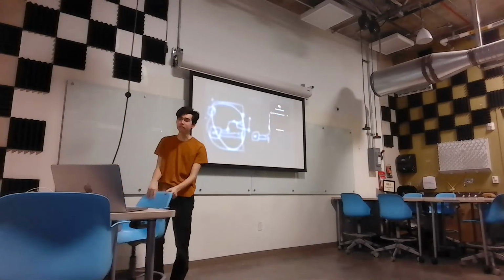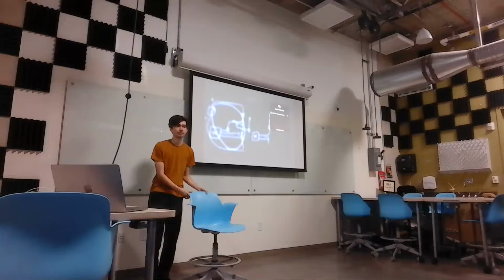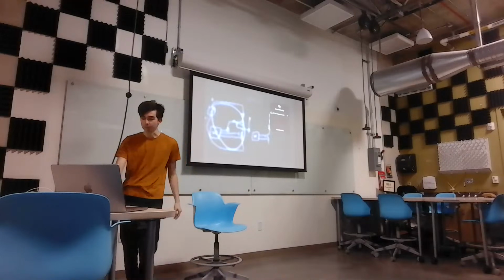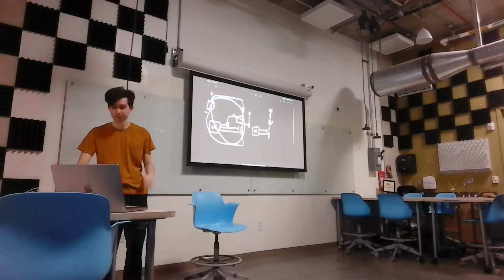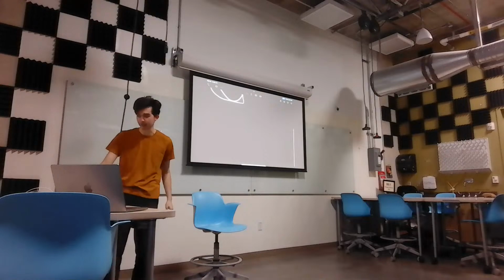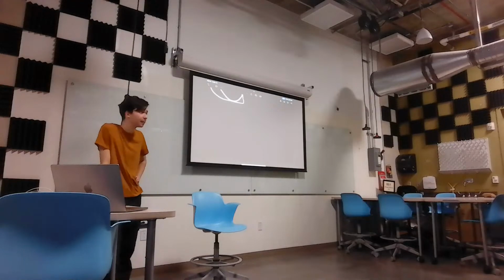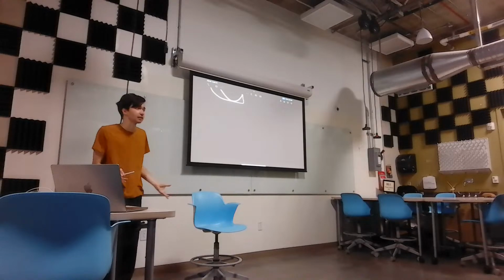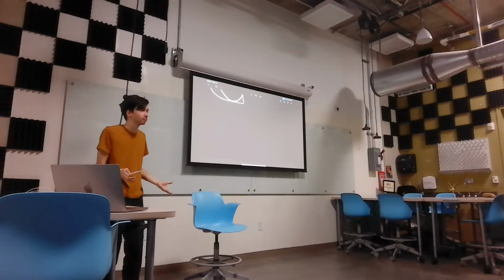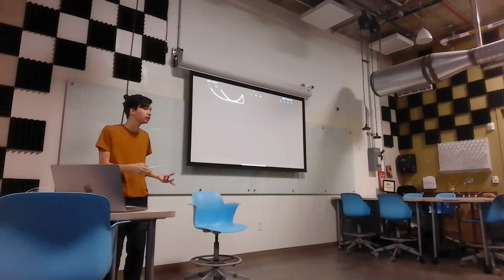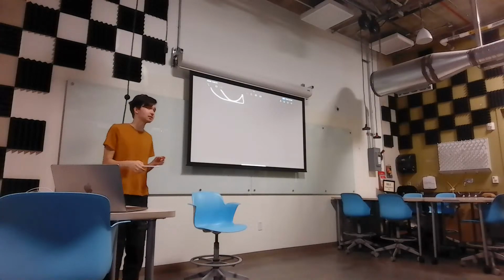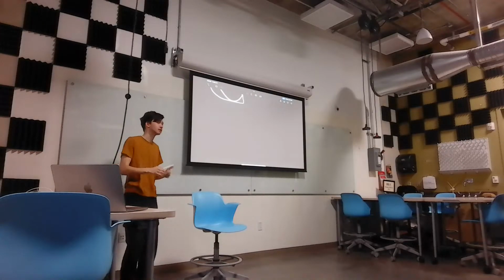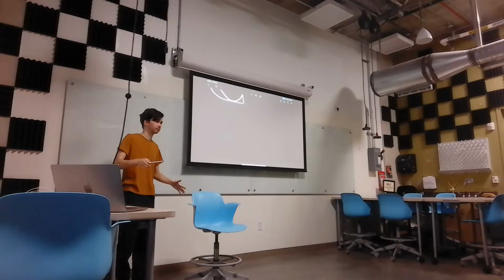So, everything dealing with computers is finite, right? We cannot have infinite precision in anything. Everything has to be finite. That goes for time as well. We're doing PWM at some frequency. How many duty cycles can we have? In our case, at 300 kilohertz, only 160. You know what that means? There are only 160 voltages we can output.